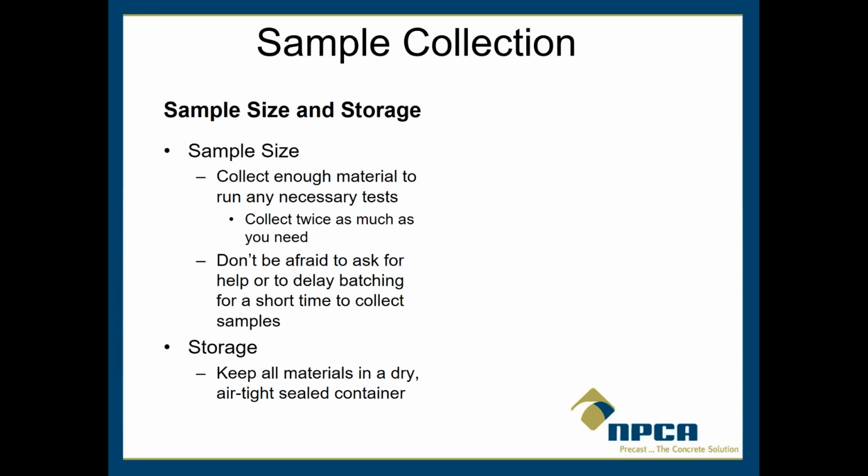And then keep the materials in a dry, airtight, sealed container. We recently had some concrete delivered to our lab from Europe, and it was some concrete that was 2 weeks old that had not set up, and so we actually put that in a sealed bag and then put it in another container, shipped it to our lab in Cambridge, and when the concrete arrived, it was still plastic.